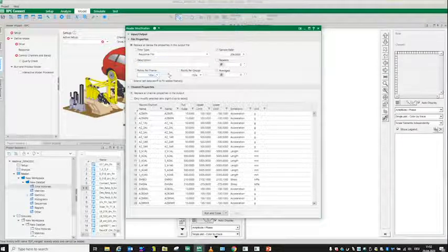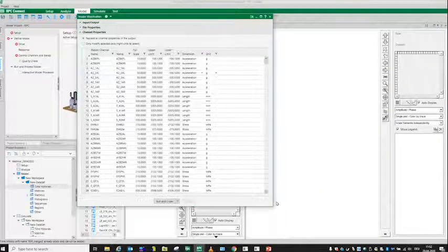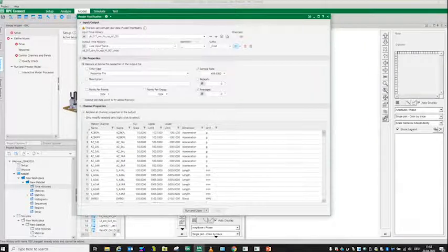The same for the file properties. If I set my sample rate to 409.6, for instance, and say, okay, the rest is fine, I don't have to look at this anymore. I click on that, and now I get more of a chance to have a look at the channels much better and more effectively. Of course, every window can be extended, so this is nothing we have to mention. But this is the way you can work more efficiently with the software, having a look at your files.